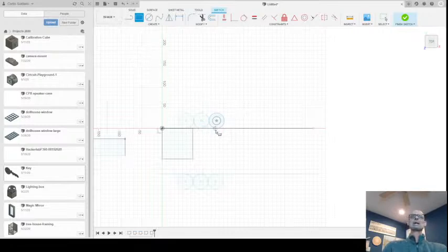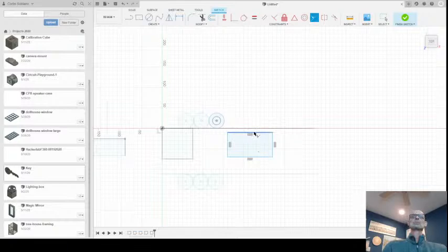So I want to put my junction box down in here somewhere. This will allow me to connect my wires. But I want to ensure that it's aligned to this same guideline that I have up here. So I can choose the collinear constraint, choose this line here, and this line here, and it aligns my electrical box to the bottom of this guide point, or the wood that holds the light bulbs and what have you. So that is an example of the collinear.